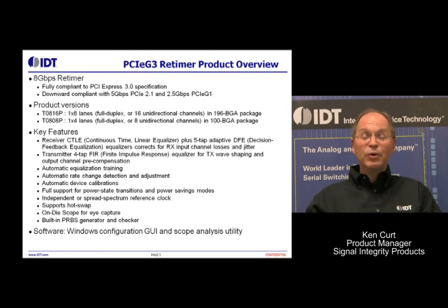And this is very important. If you think back to that blade server application where you have retimer parts on 2 blades at each end of the channel, from the transmitter side you can now generate a pattern with the pattern generator function. That pattern can output a signal, and you can adjust the output swing and emphasis characteristics, the slew rate. You've got full control over the output characteristics.